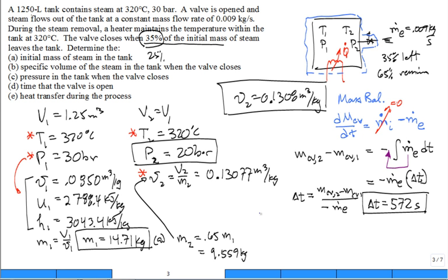Would it be something like the rate of change of energy in the control volume with respect to time is equal to the rate at which it's flowing in with heat minus the shaft power out plus it flows in with its enthalpy in, specific kinetic energy in, potential energy in, minus the rate it flows out. This is an inflow. This is an outflow of its enthalpy exit, kinetic energy exit, potential energy exit.